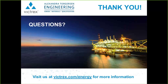Fantastic. From my point of view, the only suggestion I would have is, if you want to truly test below the TG of a material like PEEK, to look at different types of chemical degradation. So maybe increase the H2S levels or increase the aromatic levels or something like that, so that you're driving the correct chemical change even at temperatures where you don't normally expect a reaction to occur. Yeah, that's a very good point. Right.